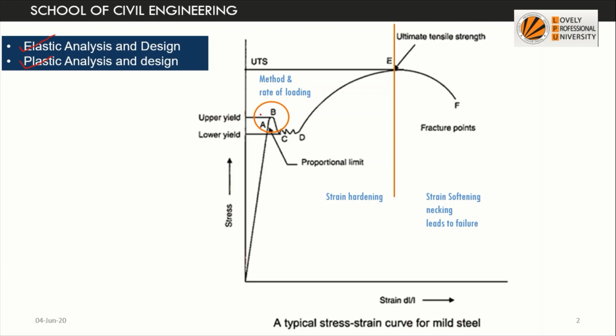As a designer, you should be very confident and very clear about the behavior of the material under the action of load. Here the material is structural steel, and for testing its properties there is one good test, the tensile strength test, which we do in a UTM. A uniaxial load is applied on the specimen, continuing till failure takes place, and simultaneously we draw the stress strain curve. Eventually we get a stress strain curve similar to this. This is not the exact variation, but similar to this we will get.